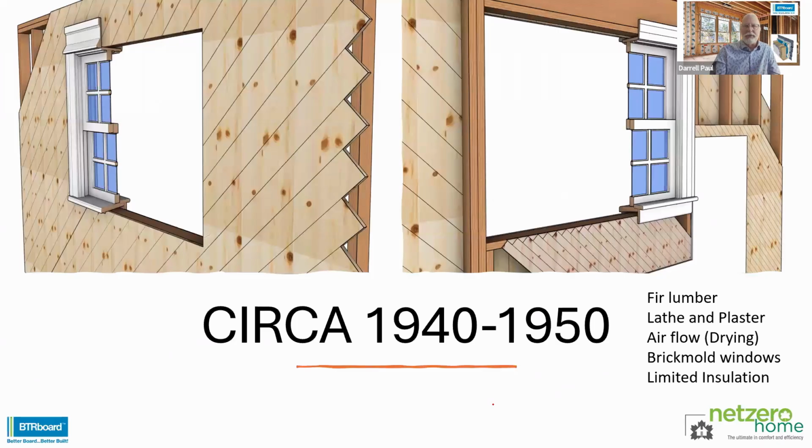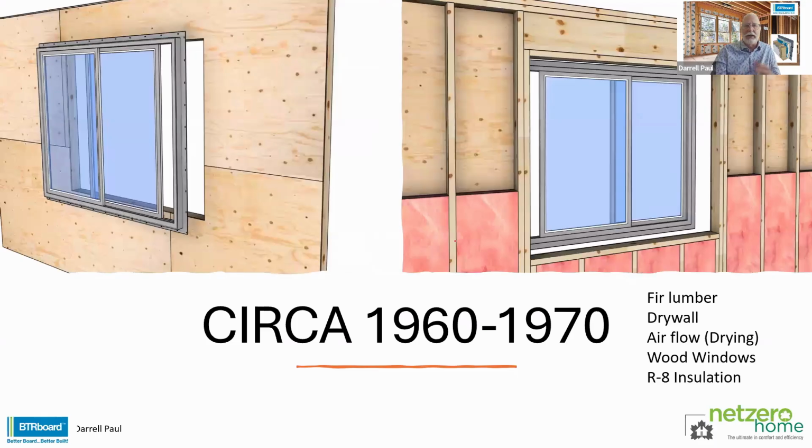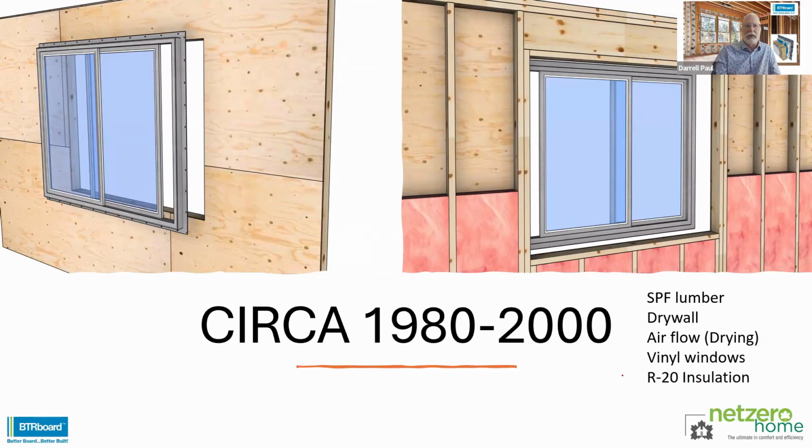We don't have time to go into all those details, but just to wrap up, this is another example of various construction methods. When you look at older windows like this, you had lath and plaster on the inside of the walls, and you had these old fir windows and fir construction, which was pretty durable. These are the things that you're going to find in older buildings. Then as you move up through the years, you're going to see things change. You're going to see a little bit of insulation in the walls, which is going to affect their drying ability. You get into newer walls with higher insulation, vinyl windows, different things like that.